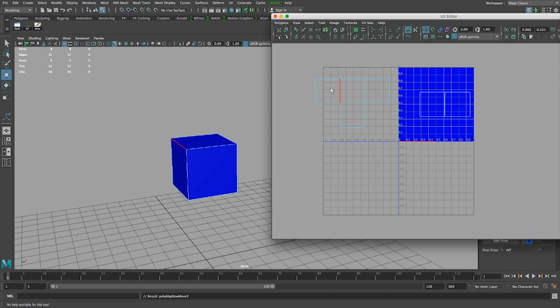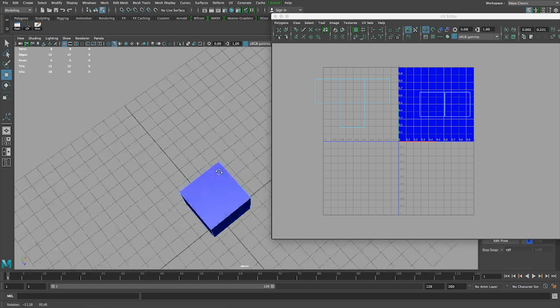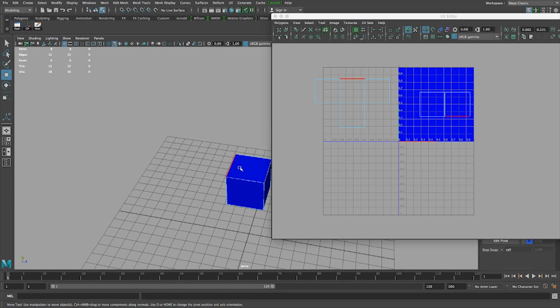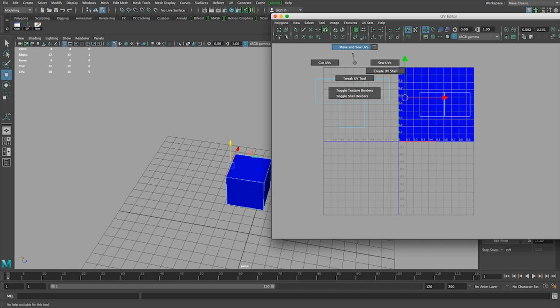So try to get this, well, whatever, upside down plus. We have this? Yeah. Okay, so now the last one, and I can also do it from here. I don't actually need to look where they come from. I did it just to illustrate. I can just go edges, click on this edge, and then either here or Shift, Move and Sew UVs, and I get this plus now.